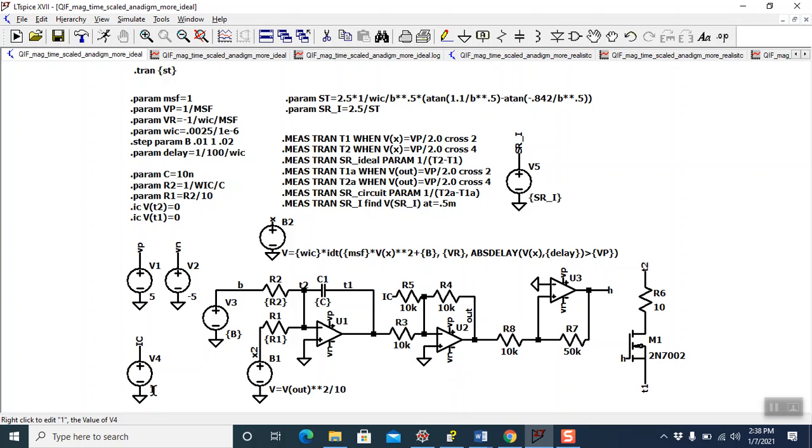V out. So if I have 1 here, when this resets, the 1 times a gain of -1 gives us an output of -1. That's where we get our V reset. And the width of the hysteretic curve, the high switch point, gives us the V peak. Now something else here is a completely ideal circuit where you can actually scale things for magnitude and time scaling. I'm not going to go into that too much.